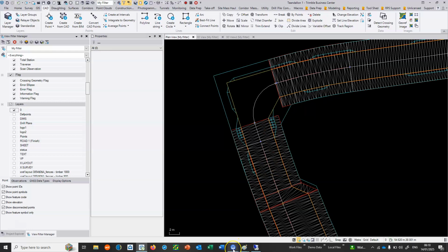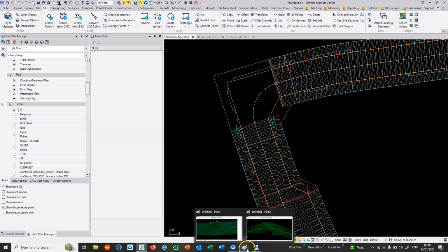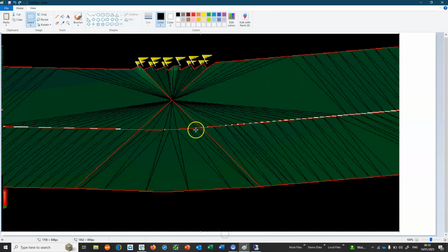So the sort of things that we are seeing happening, if I just flip up a couple of examples. Here we've got a center line string, and the radius of that center line string is less than the half width of the road. And what you basically get is this erratic functionality on the actual channel occurring.